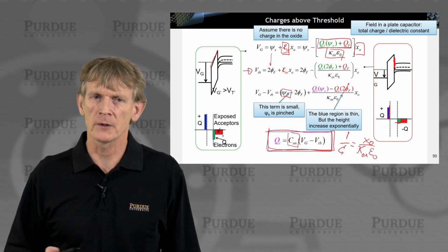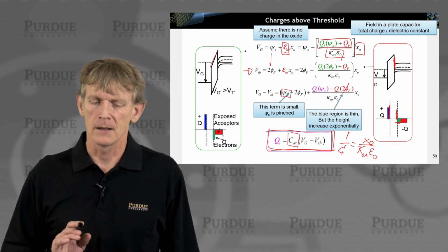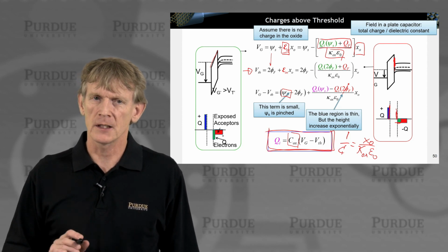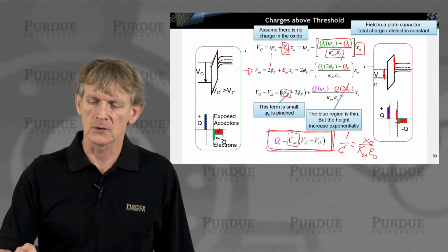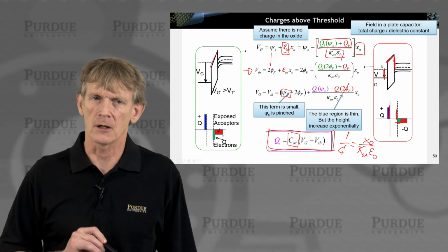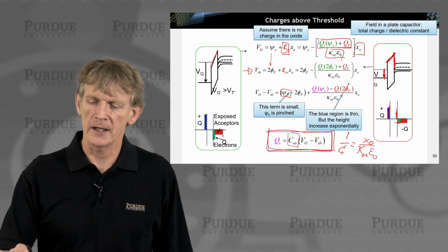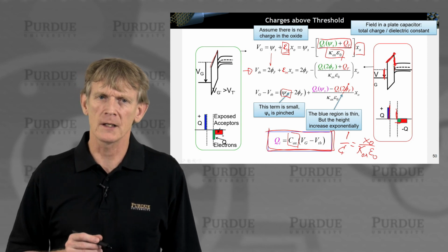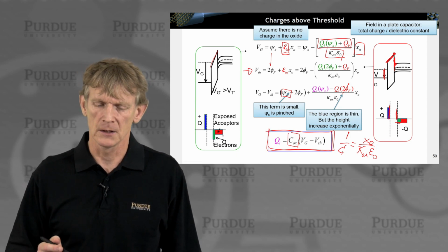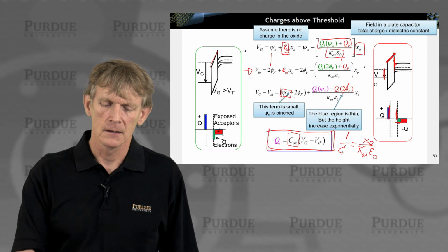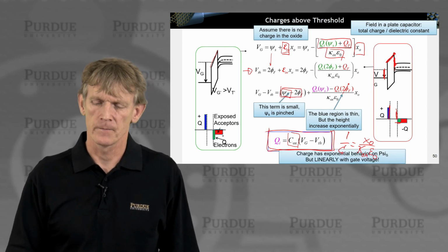So we can pile up exponentially large charge directly against the interface. So really now, all the potential that you're going to drop by the gate is going to pretty much drop here over the oxide. So a tiny little bit of wiggle will translate on this side into an exponential growth of charge. So the additional potential drop will be minuscule. So you can barely get psi S over to phi F.